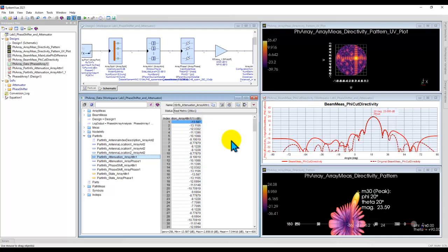Our earlier simulation was using minus 12 dB, out of which 1 dB was the insertion loss. So the actual attenuation required was 11 dB. But here it is using 13 dB. So what's going on, right? There is some issue. But before we get to resolve that issue, look at attenuation.